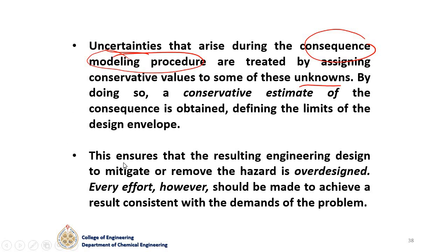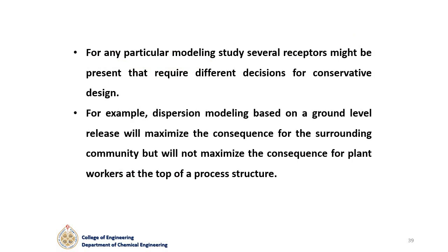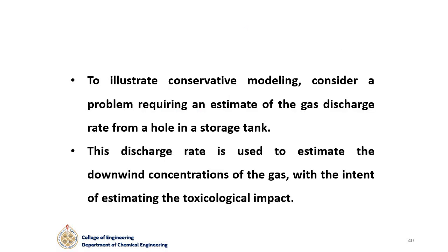So what I need to do is always work on the worst case scenario, where I try to mitigate and avoid the hazard, even at the cost of over-designing, putting more consideration into safety. That will all appear from my modeling study and my dispersion modeling. So my design will depend on all this information. I should consider a much better design, to be more conservative of what's going to be happening.